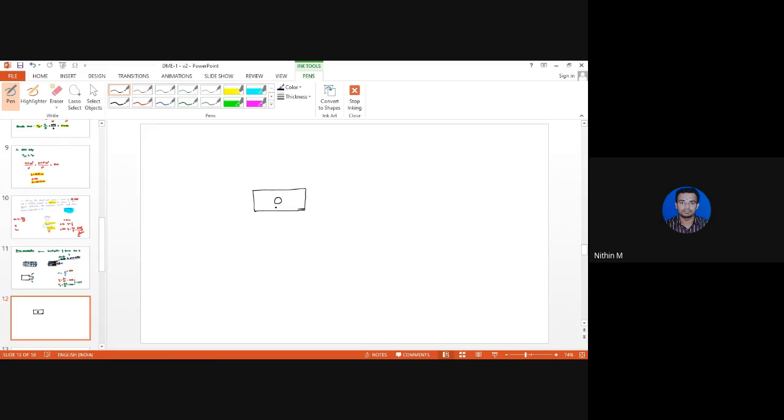Now this is a very difficult task. So what will we do? There we have no other option than having a plate with a hole drilled at its center. Now what will happen in this case? Whenever the stress lines go here, they are supposed to cross this component this way. So here there is a reduction in cross section, and here there is an increase in the magnitude of stress, which we call stress concentration.